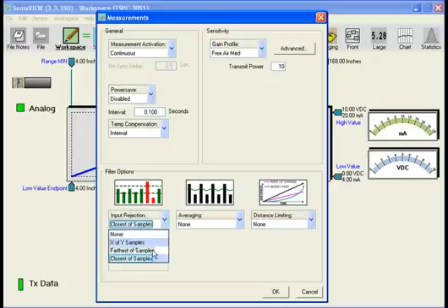In the case of furthest, it would be the same. You might be able to see that those two could be used to pick the peak of a wave or trough of a wave. The X of Y samples is a little more complicated. The default is typically 3 out of 4, but I like to use 2 out of 2. What it does is apply a 12% arbitrary filter. It falls out of the digital math, but when you set 2 of 2, what it says is only output a measurement if 2 measurements in a row are within 12% of each other, the 12% being arbitrary.